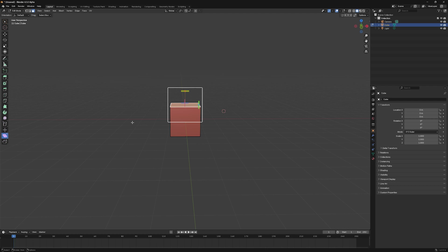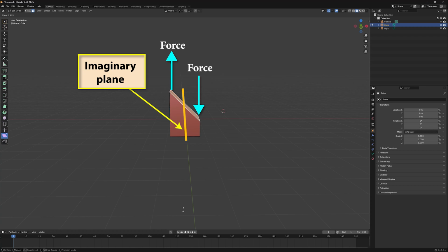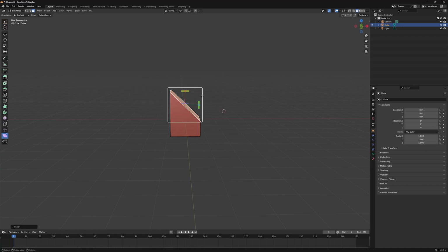At the end of each line are 2 colored bars. One bar is the color of the axis to which it is attached, and the other bar is similar in color to the axis that the selected face's edges will move along as it rotates. When we drag on this second bar, the face will reshape as it rotates. Note that the set of axes used by this tool depends on the current setting in the Transform Orientation panel.